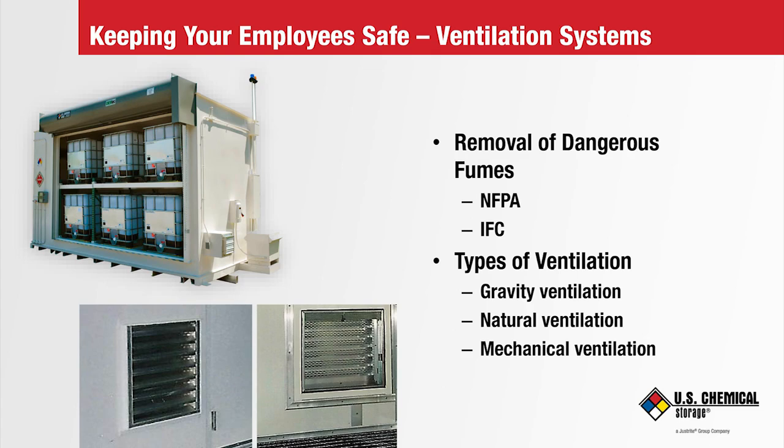Now, what has been accepted is having dual or secondary fans operate as an emergency backup or redundant system. Fan number 1 would run continuously, with added gas sensors that monitor concentration for a gas alarm, and a sensor that monitors air pressure in the exhaust stack for the number 1 fan to give a fan malfunction alarm. The gas alarm will turn on the second fan to increase the air intake. The fan malfunction alarm would also turn on the second fan to maintain the air intake.